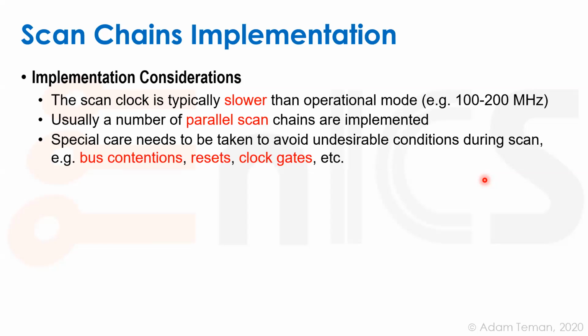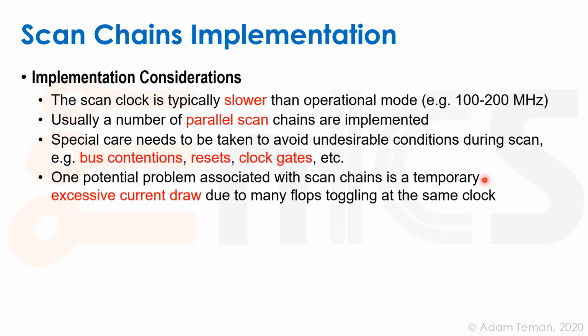And there are different types of design rules that you should make sure are kept. You don't want a combinational reset that's going to reset your flops during scan. So these types of things either have to be eliminated by design or be bypassed during scan mode.